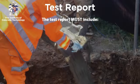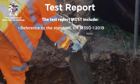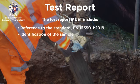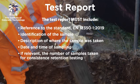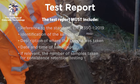The following information must be reported on completion of the sampling. Reference to the standard EN 12350 Part 1. Identification of the sample. The description of where the sample was taken. The date and time of sampling. If relevant, the number of samples taken for consistence retention testing.